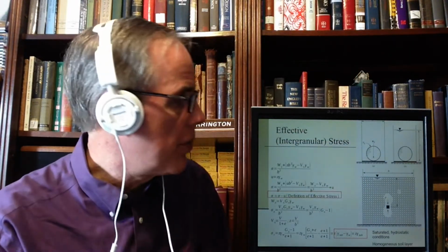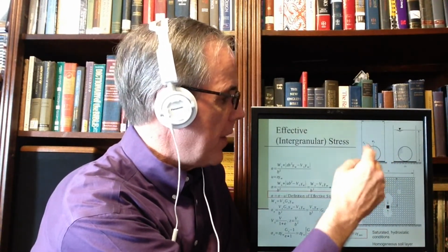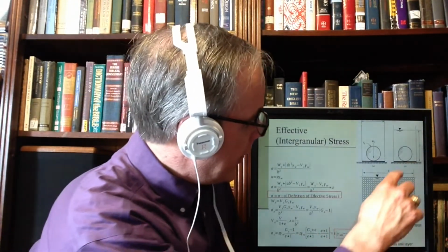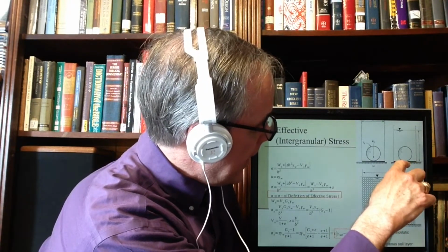If, however, we were to fill with water under it, the volume of water that it displaces would put an upward force on that weight. And that would reduce, among other things, most importantly the contact stress between the sphere and the bottom of the tank. Well, in soils it reduces the stress between the soil particles, since there's usually no real bottom of the tank.